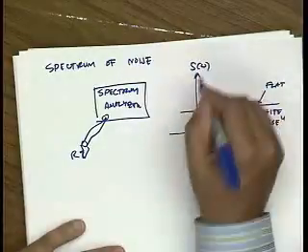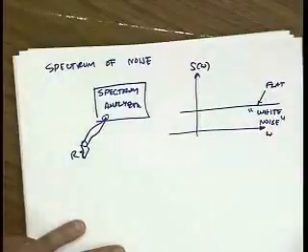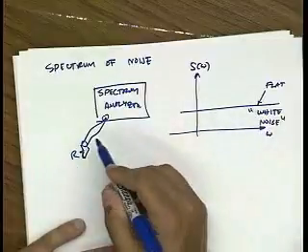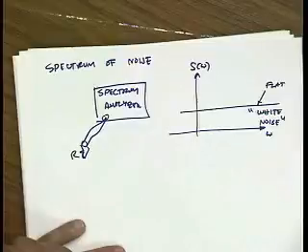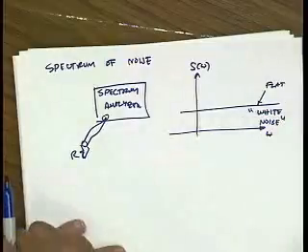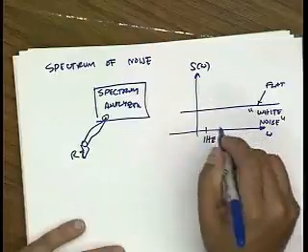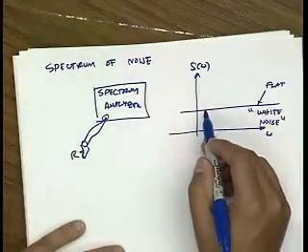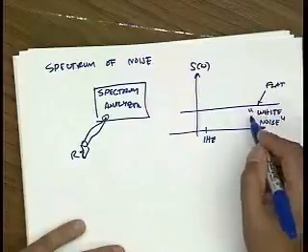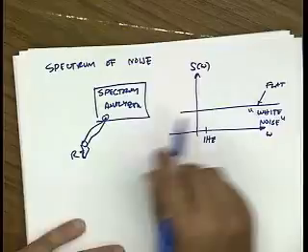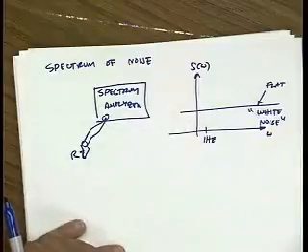So this is the spectrum as a function of frequency. This is the frequency axis. All right? In other words, a plain vanilla resistor generates flat spectrum noise. So if I look at 1 hertz, let's say here, it has a certain amount of noise power associated with it. If I go to 10 kilohertz, it's the same. If I go to a gigahertz, it's the same. And in fact, if you go up to 10 gigahertz, even up to a terahertz, it's practically the same.